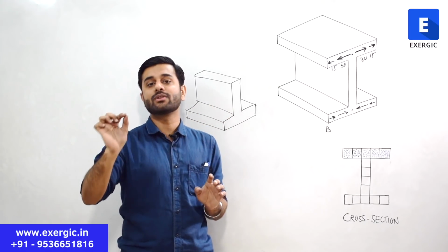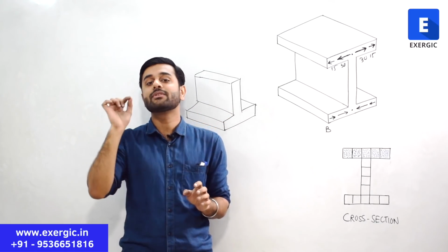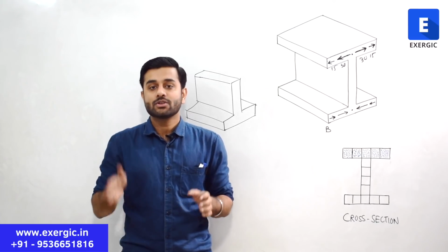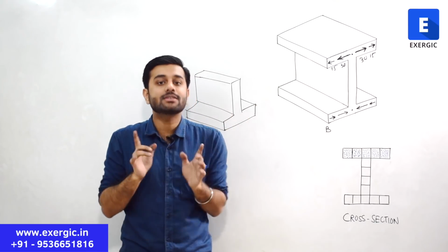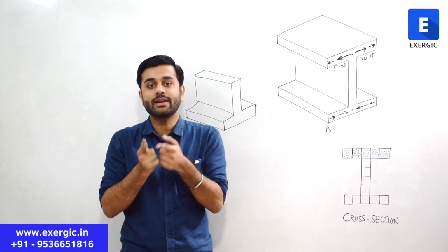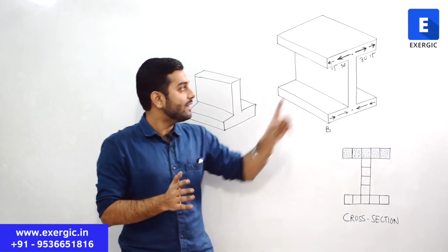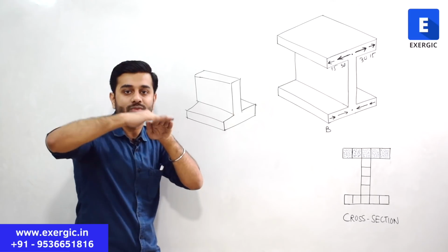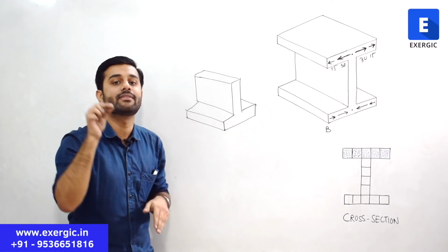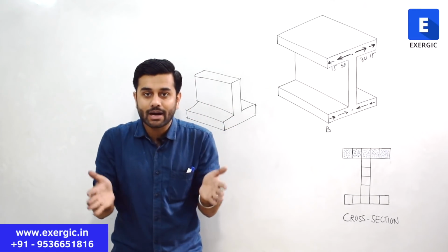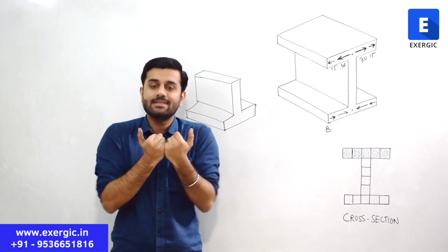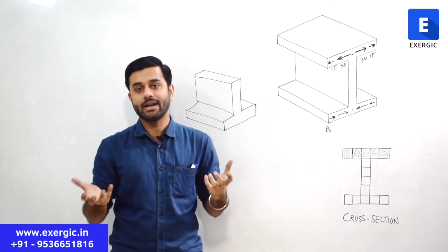In one, the force F1 minus F2 was 15. So in 5 of them combined, it is going to be 15 multiplied by 5, which is 75. So F1 minus F2 for the top flange is going to be 75. And some part of this section has to resist that F1 minus F2, right?